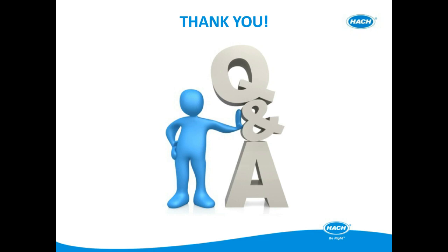Okay. Another customer here who says that we have a DAF that is currently being challenged by algae. The issue we have at the moment is that the turbidity off the DAF decreases at higher flows but increases at lower flows. Could the retention time in the DAF be an issue, or is it more likely to be related to the upstream ozone dose? So there's an upstream ozone dose as well as that.